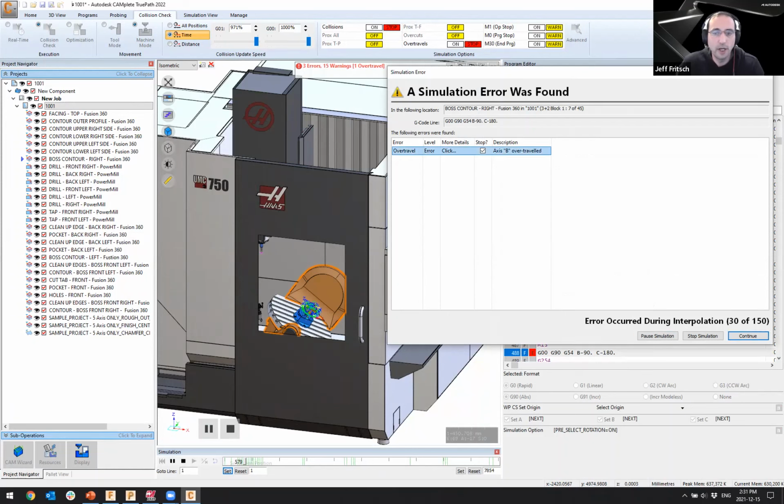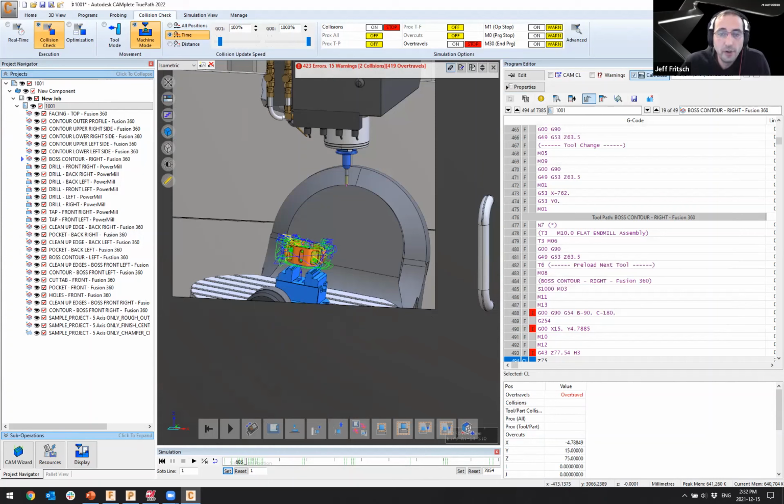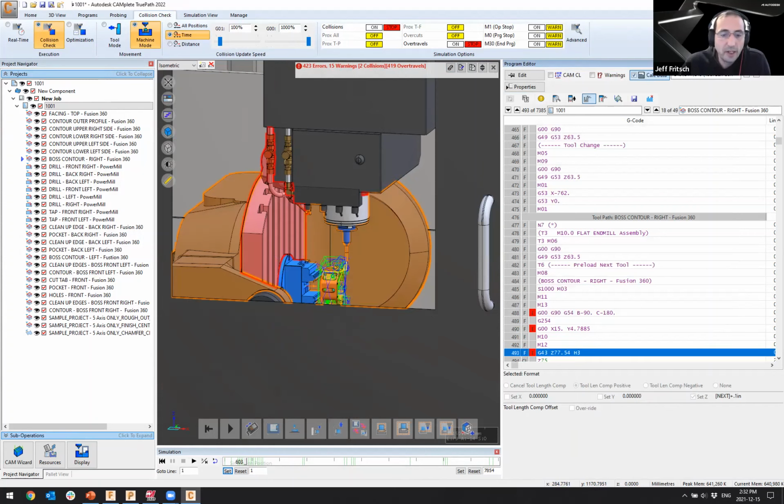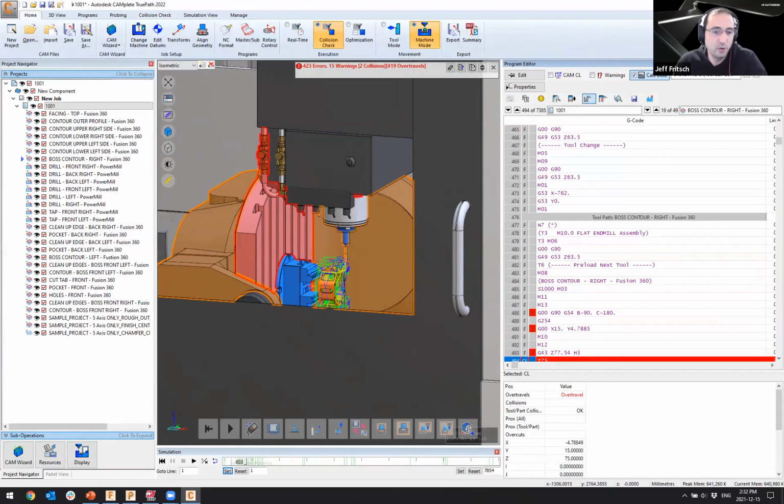So really what we want to keep is the intent of the toolpath. So we definitely want to keep this toolpath, the way the tool is going to move into the material, exactly the same, but we just want to be able to pick now the alternative solution and really make those existing toolpaths fit, without having to go back to the CAM system.